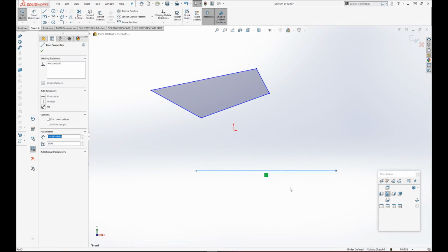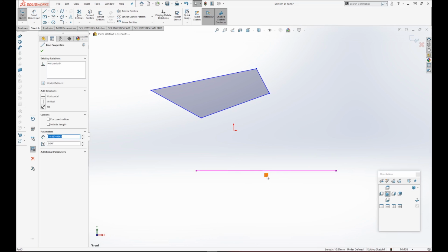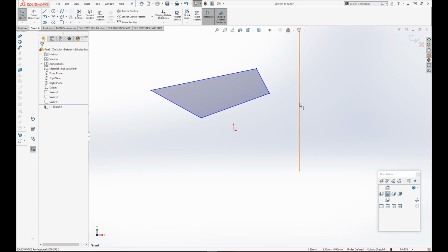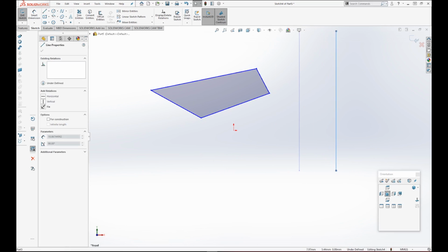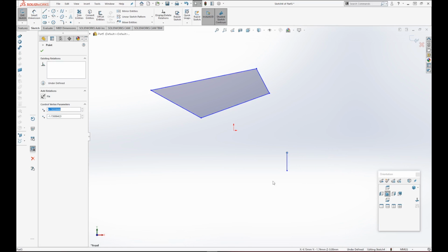So as you guys can see, relations can be pretty important, but let's say you wanted to delete it. Go ahead and click that green box and hit the delete key, or you can go up to this little window right here and hit delete. All of your relationships will show up in that little box. You could have multiple relations on one line, and they can also conflict with each other. So you could change it all up in that little box or in the little green boxes next to the line.